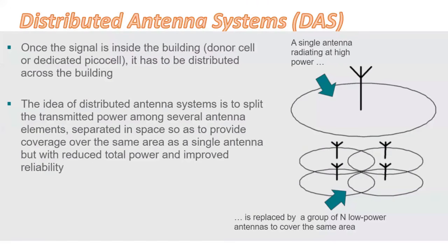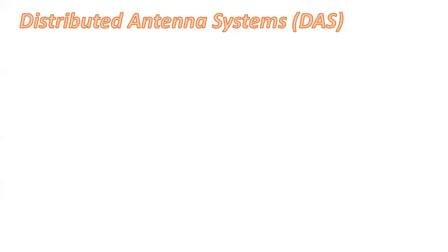So what is shadowing? Shadowing basically refers to loss in signal power due to obstructions in the path of propagation. There are various ways to overcome shadowing, but the most effective way is line of sight propagation. With the help of DAS, we have more chances of line of sight and we can avoid shadowing. And one more thing, as you know, free space path loss, right?